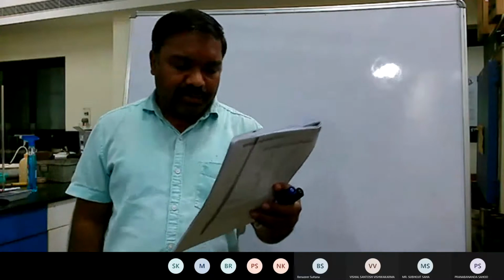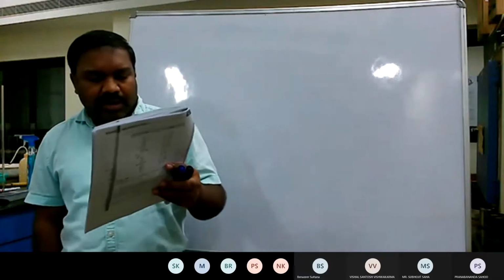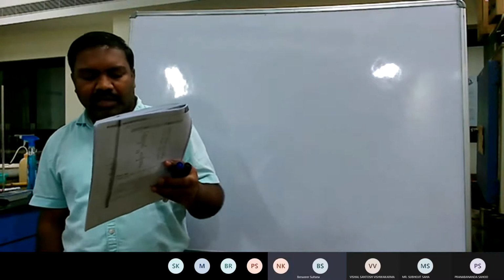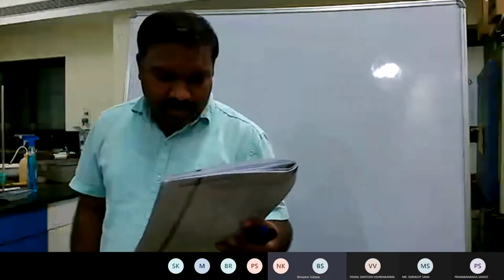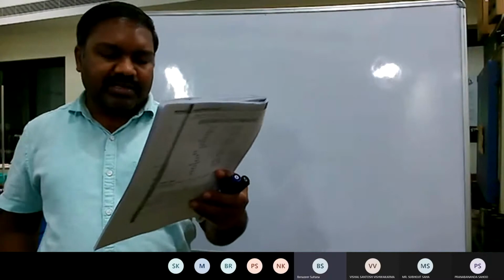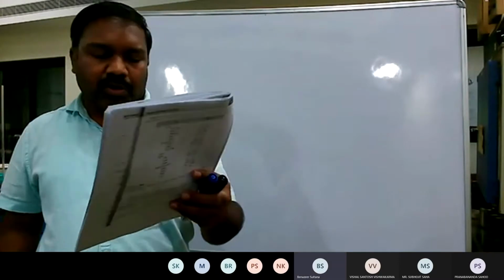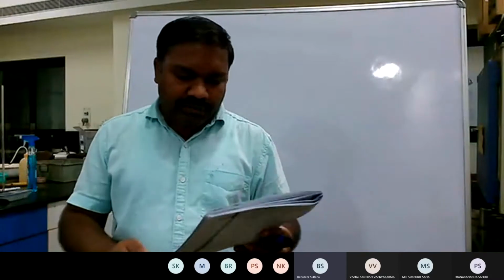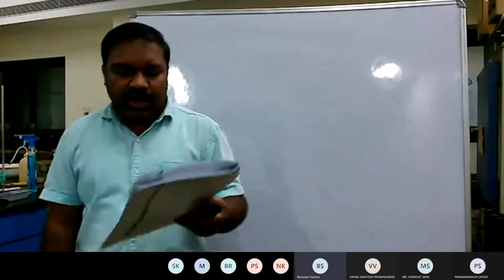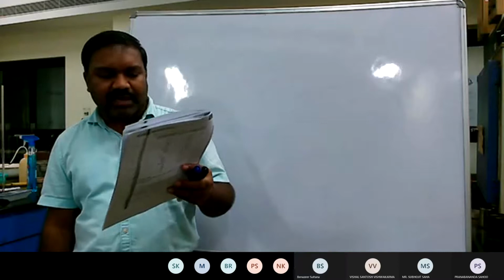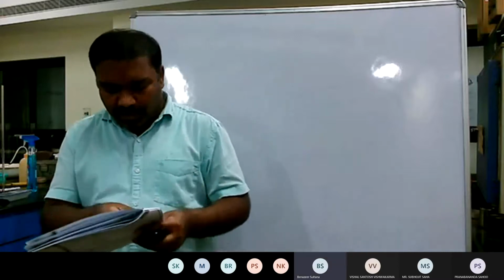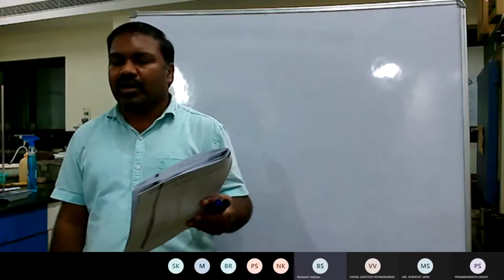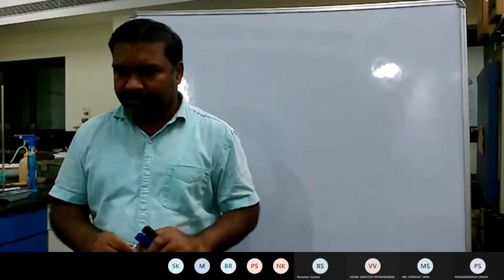If you look carefully, on this element there is 100 kPa in the vertical direction and 40 kPa in the lateral direction, and a shear stress of 20 kilopascals, both clockwise and anti-clockwise, is acting. As the shear stress is acting on the element, it should be clear by now that this element is not subjected to the principal stresses.